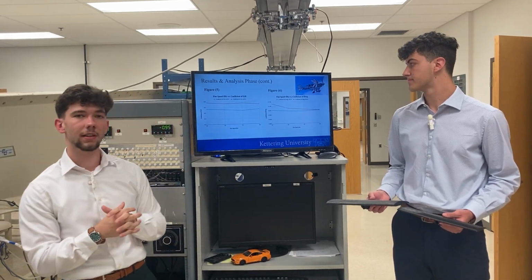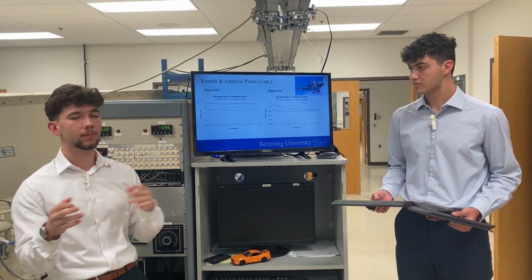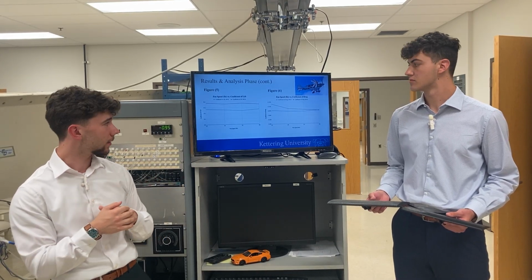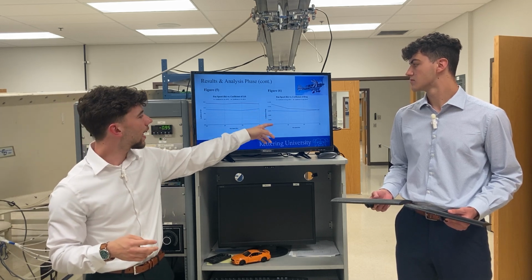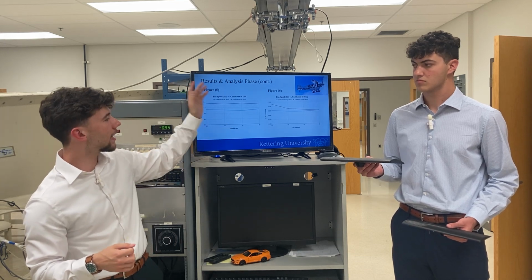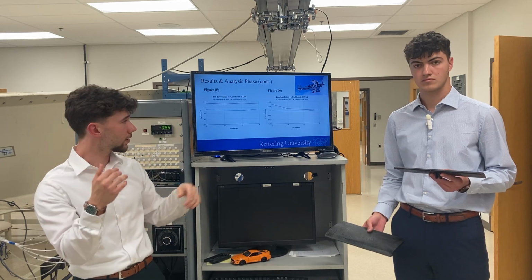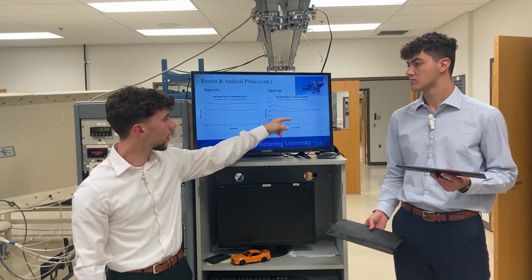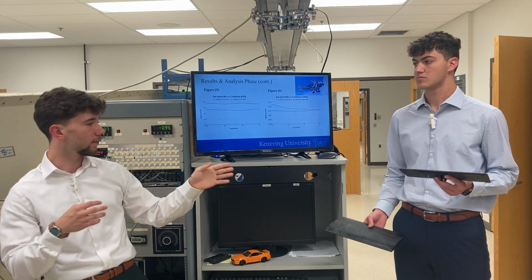However, figure 6 allows us to draw real implications for what type of aspect ratio we would want in a real-world application. As we can see, the lower aspect ratio foil at low speeds has a much lower coefficient of drag. However, as we get to steadier high velocities, the foil with the higher aspect ratio decreases to a point where it then has a lower coefficient of drag compared to the fat foil.